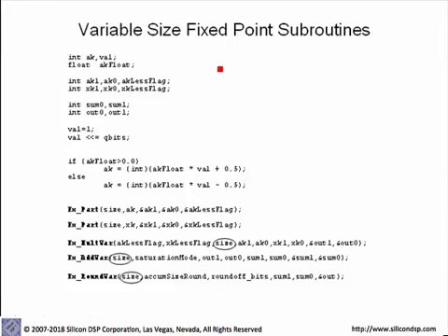We note that in many cases the architecture of the filter has to be changed in order to support high-speed operation. For example, in the case of FIR filters, you have to do a retiming and change the architecture in order to be able to operate at very high clock speeds.